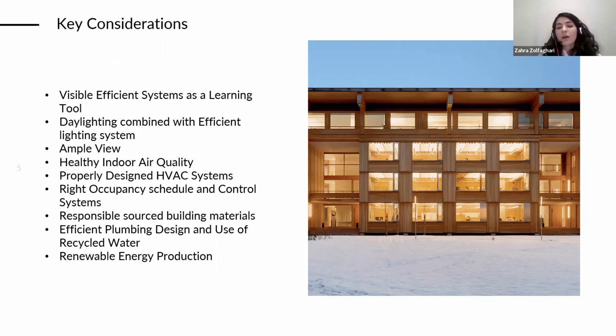patterns. But overall, the EPA advises several strategies like using materials with low volatile organic compounds or VOCs and other toxins, installing properly designed HVAC systems that control temperature and humidity, changing filters regularly, and incorporating outdoor air for ventilation, and also removing odors and pollutants through pressure control or filtration and exhaust fans.